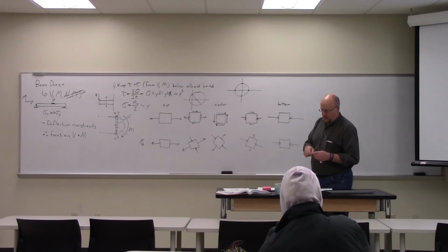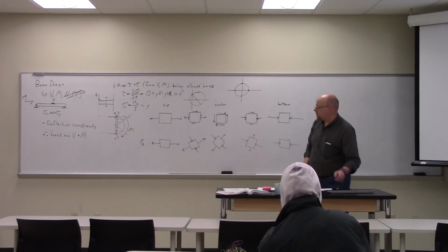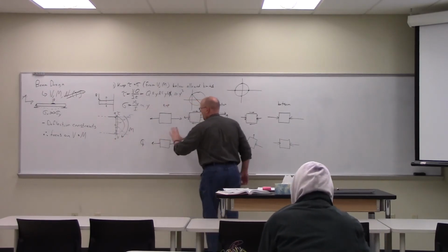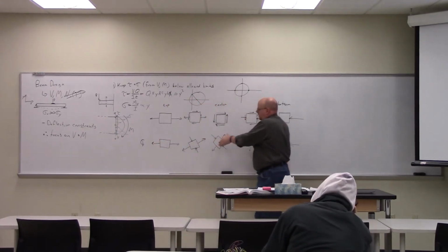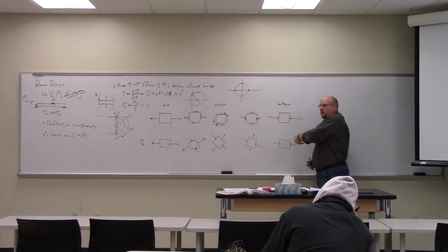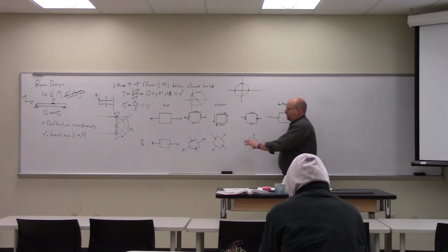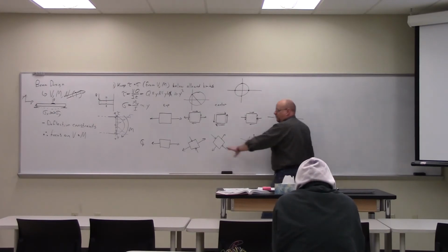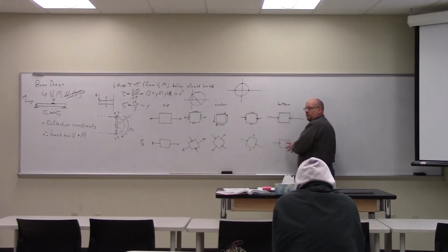So as I move from the top to the bottom of the beam, I go from this to rotating around to this in terms of my principal stresses. Okay? So my principal stress is effectively rotated by 90 degrees and shifts from tensile to compressive.